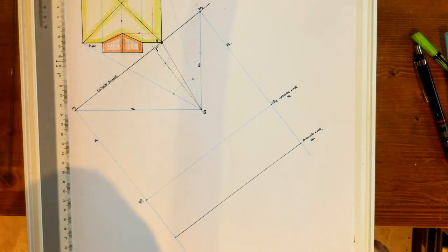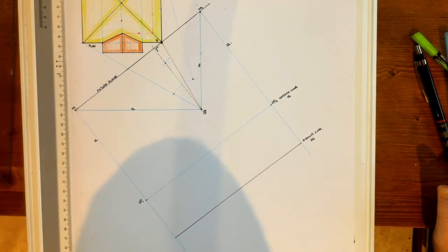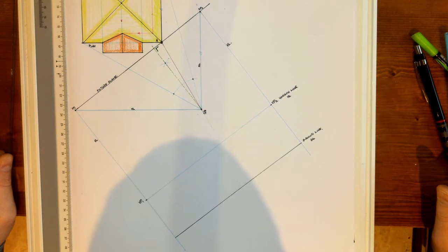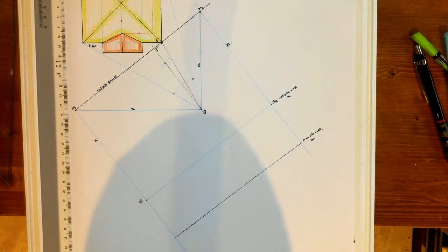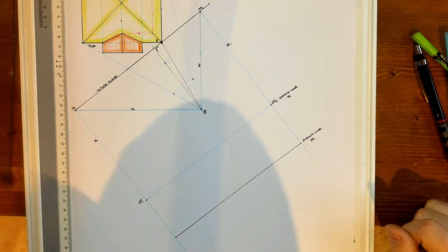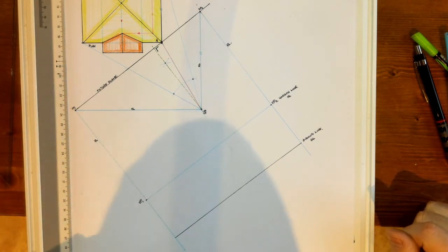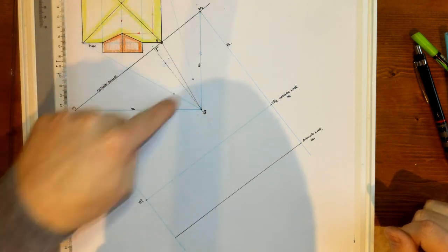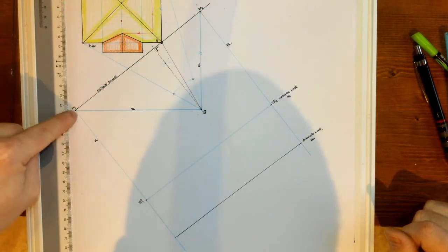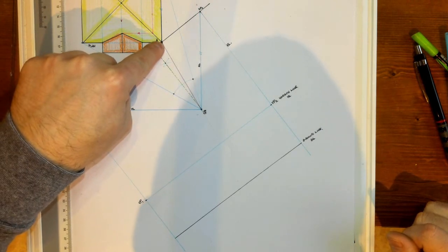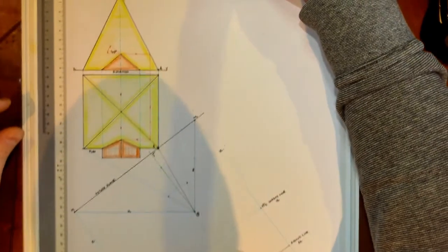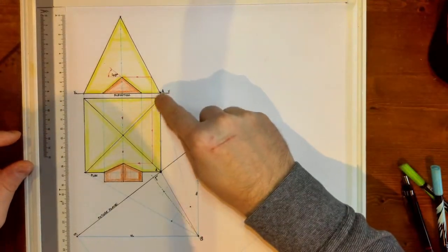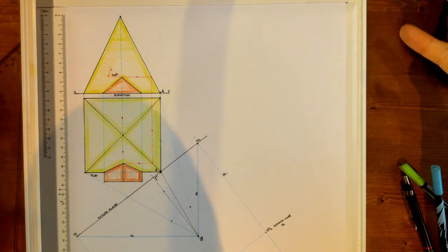Now, so from there, what do we need to do? Well, we need to start taking projection lines from our plan view back to point S. Okay, but before I do that, there's one step, and I recommend you do it at this stage. Identify the point that is on your picture plane in the plan view. So this is the plan view. So what we have here is our picture plane, and it passes through point A. Okay, and if we looked at point A in the elevation, we will see that point A is here, and it's on the ground, and there's no height associated with it.